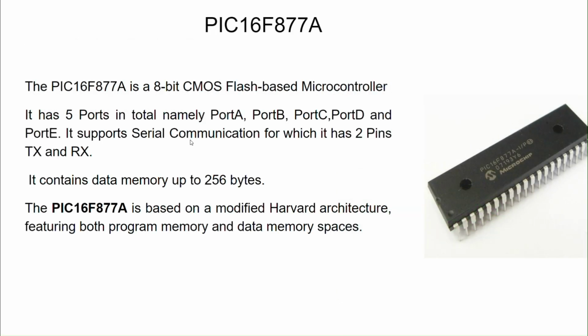The PIC16F877A microcontroller is used in this project. The PIC16F877A is an 8-bit CMOS flash-based microcontroller. It has 5 ports, namely port A, port B, port C, port D and port E. It supports serial communication, for which it has 2 pins, transmission and receiver. It contains data memory up to 256 bytes. It is based on a modified Harvard architecture featuring both program memory and data memory spaces.